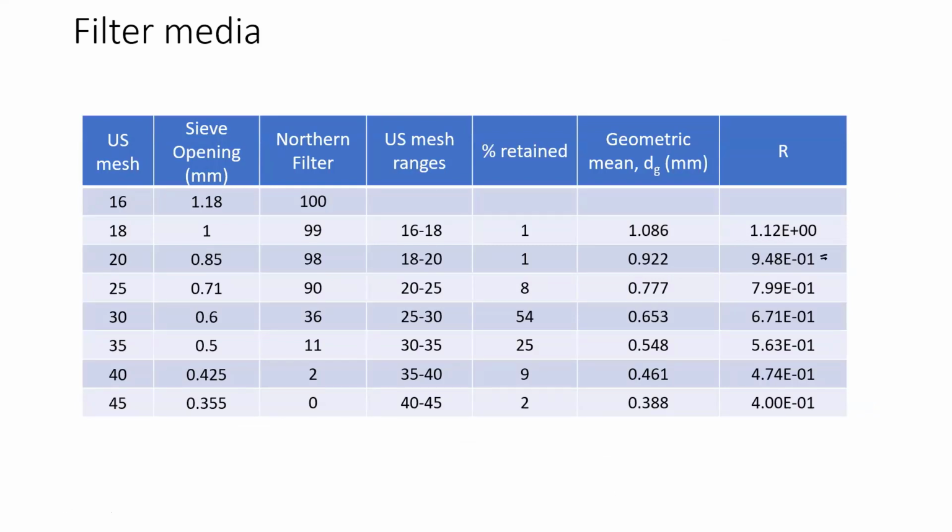Okay, so this here is just the 0.75 times 0.922 times 10 to the minus 3 meters times our approach velocity divided by the kinematic viscosity. Okay, and that is equal to this value right here. So we're going to do that for each. So that's why we want the spreadsheet. So that gives us the Reynolds number. The next thing we need to do is calculate the drag coefficient.